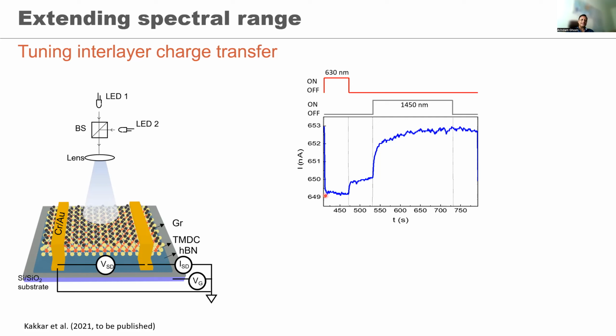We decided, okay, is there a way we can sensitize this structure to infrared radiation by shining a light which will take those electrons out and give them sufficient energy to come back to the chalcogen layer, and there it combines with the holes, and hence we can actually look at a recovery of the dark current using infrared radiation. Turns out that was possible.